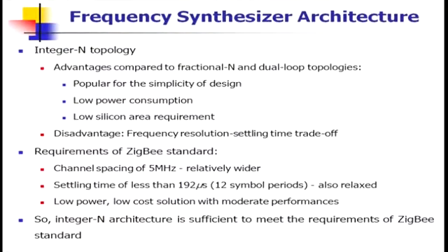So with this, let me give you what kind of specifications you should start with. I say this for Zigbee applications. My divider will be using an integer mode, because my spacing is 5 megahertz. So 480, 481 up to 495, that is good enough for my 16 channels. Clear?